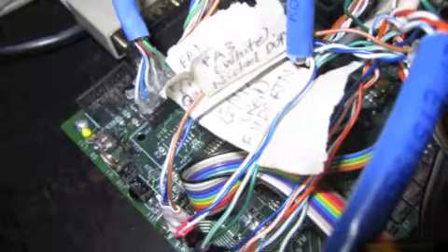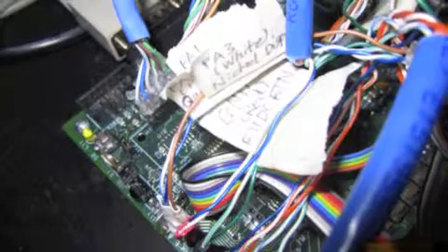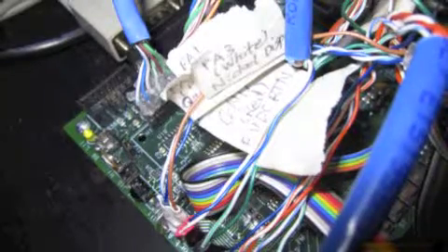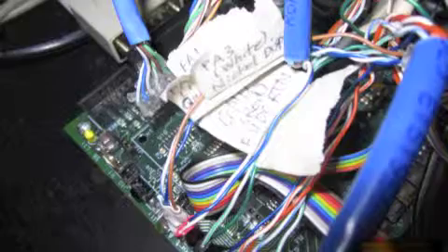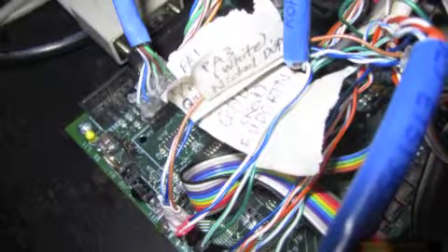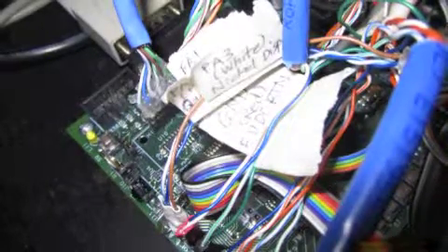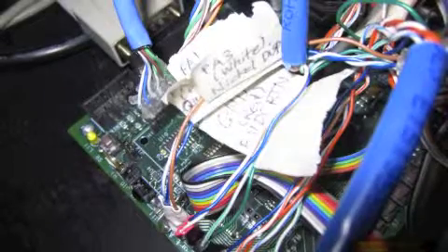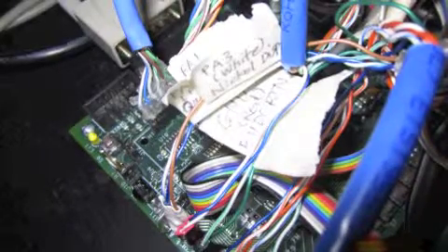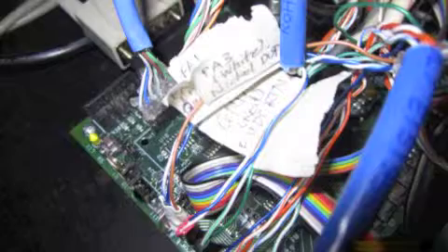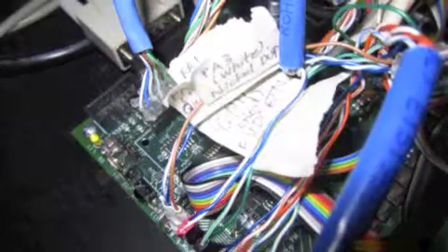The AVR board is the central nervous system of our project, with our microcontroller acting as the brain. It receives input from and interprets the signals of the coin machine, card reader, and keypad, as well as managing the server data and vending cycles. It uses these to control the temperature control circuit's fan and the screen outputs of the LCD. From the microcontroller goes the connections needed for the LCD, which is used to display card reader commands and notifications.